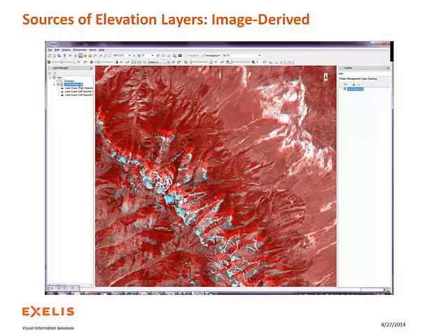A lot of people really like to use that in this environment when they're doing some tie point refinement, which is something that you can do before extracting the DEM, is examine the tie points in 3 dimensions to adjust the surfaces to get them just the way that you want them before extracting the actual DEM. So that's why I put that up here.